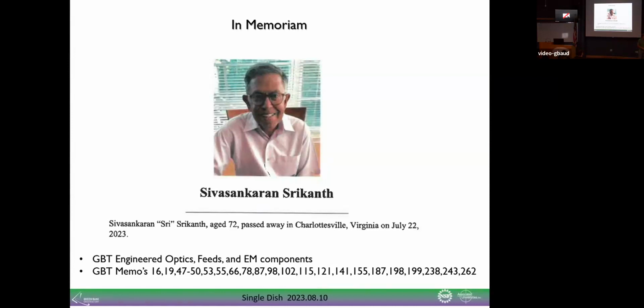We do the same thing with low frequency receivers and coax. We try to put a long bit of coax there that gives us high thermal resistance, and then use different stages of the refrigerators to lower the load on the first stage. And that's kind of how we do it.